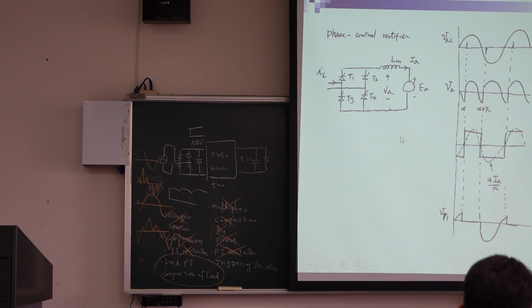So do you think your power factor can be increased or decreased if your firing angle is delayed? It is decreased. For example, if you become 60 degrees, then it becomes 0.5. If you become 90 degrees, it becomes 0, right? So the more delay, the worse the power factor.